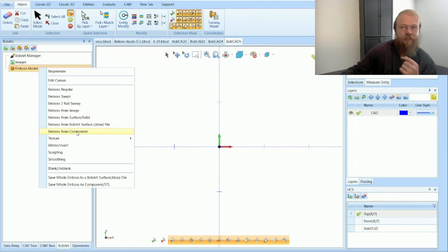You'll have trouble trying to extrude cut anything away from it. You can add to it and then save it as an STL file again, and you can keep adding more to an STL, but you can't take anything away. You can't extract any edges to create an imprint of it, is what we're going to be going through.